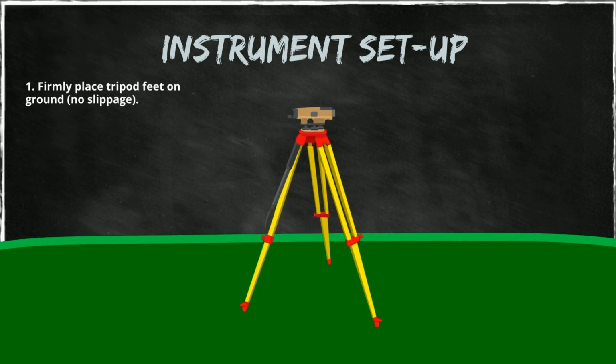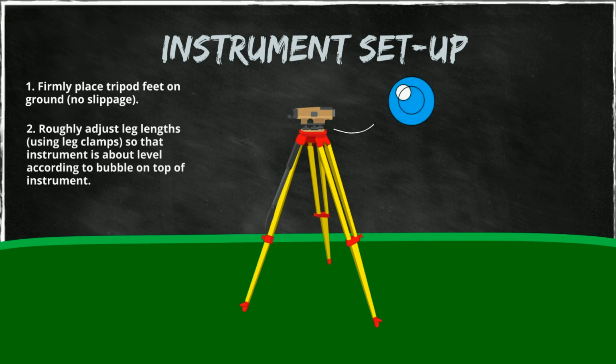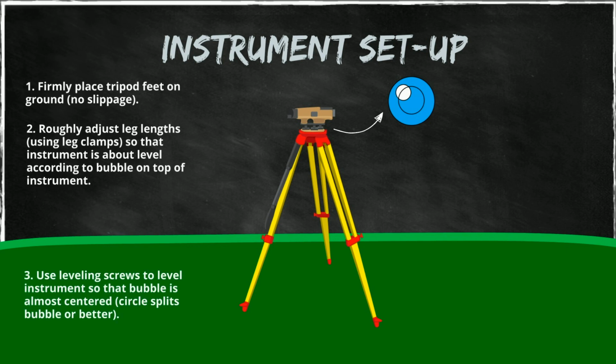Then, of course, there is the bubble on top of the instrument, and one can use these leveling screws and the lengths of these legs to bring this bubble to the center or close to the center.